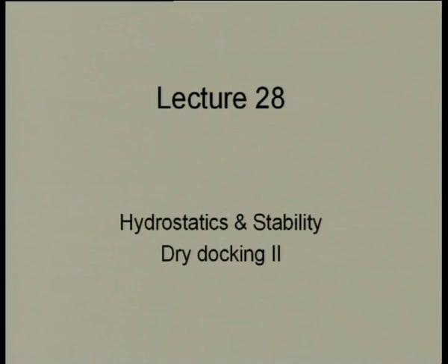Okay, so in the last class we were talking about dry docking, where we take a ship to the dry dock, which will lower the water level, and consequently the ship will keep going down till it finally touches the bottom, and then there is a reaction force which supports the ship, and consequently the buoyancy force gets replaced by the reaction force completely.